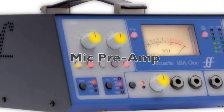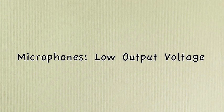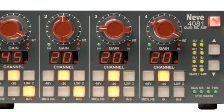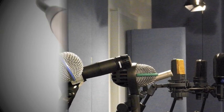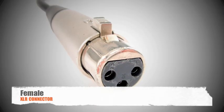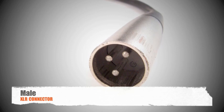Most microphones require a device called a mic preamp in order to function properly. This is essential due to microphones' low output voltage. The role of a mic preamp is to raise low output voltage into a stronger, more usable signal. Professional microphones primarily use balanced cables with female and male XLR3 connectors. Due to their enormous importance in audio productions, microphones will be discussed in more depth in Chapter 4.